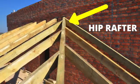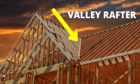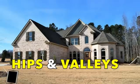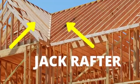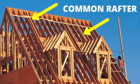To create an outside corner, a hip rafter descends from the ridge to the corner of a wall. To create an inside corner, a valley rafter does the same thing. So these roof contours are simply called hips and valleys. Shorter rafters that meet a hip or valley are called jack rafters. The rafters that go all the way to the ridge are called common rafters.